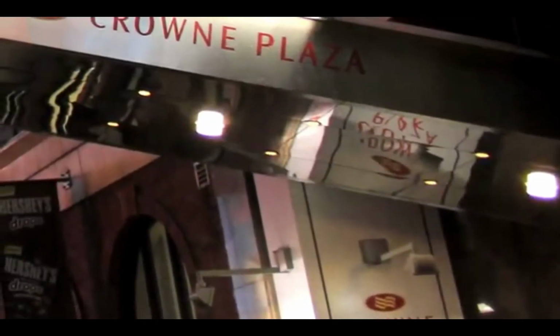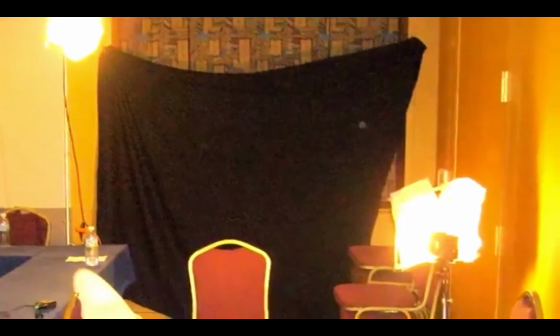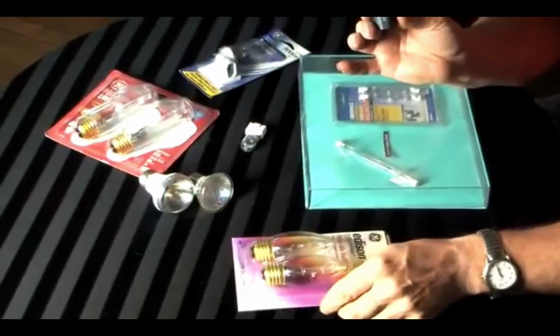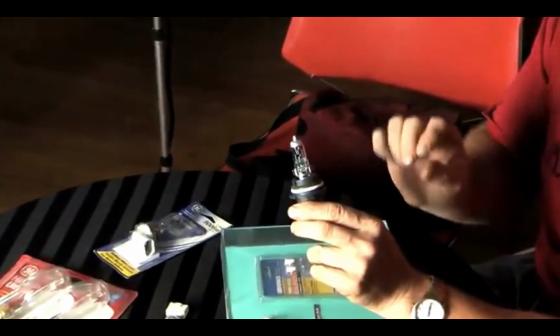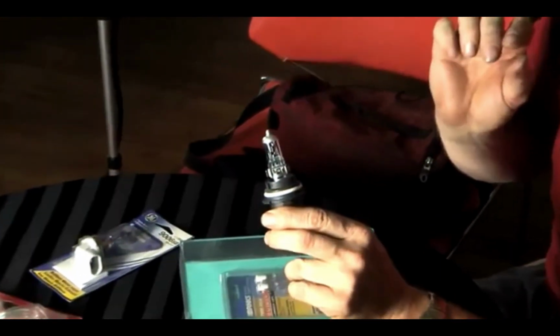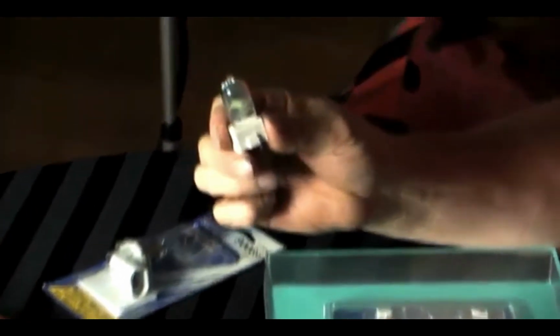The only main disadvantage of this lamp is that they run so extremely hot, and they're better off put in an outer envelope like these types are for household use. And also, you can't touch the bulbs with your fingers, because if your skin oil gets on the quartz and it gets hot, it goes through what's known as devitrification, which is what happened to this lamp. You see the quartz is all discolored and messed up.